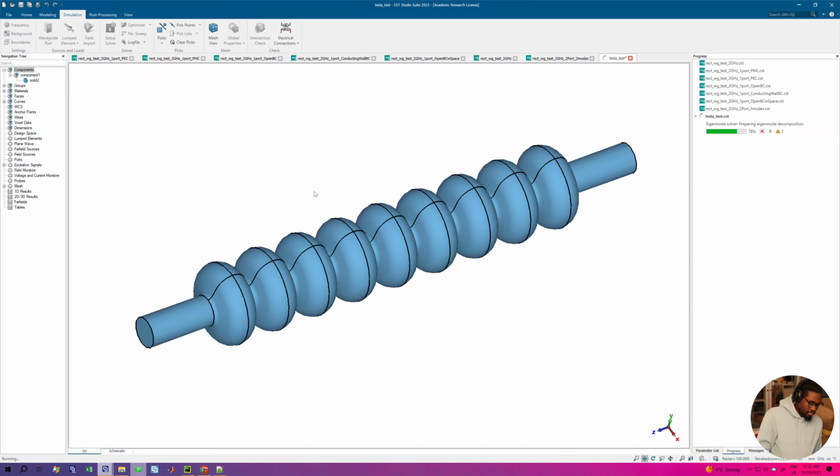And now it's done. From the result, you could see you have 1.27 gigahertz up to 1.30077. So not good because you have two modes at 1.3 gigahertz, but it's what we expect. What's the number of tetrahedrons? We have just 25,000 tetrahedrons. No mesh refinement, and you have that your pi mode is at 1300.78 megahertz, but your 8 pi over 9 mode, the ninth mode, is also at 1300 megahertz.